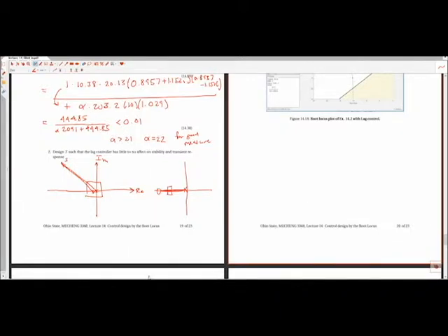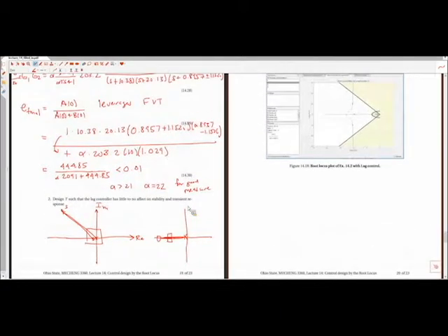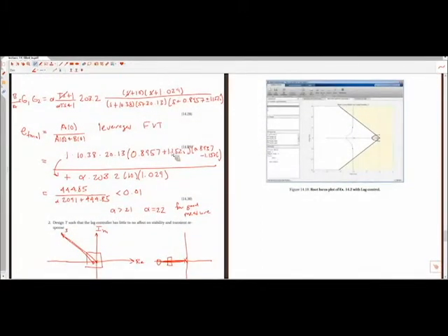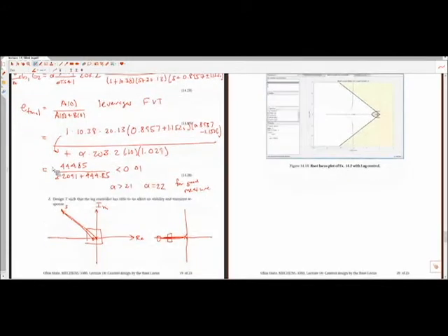So here we had a condition where we wanted the steady-state error to a step reference to be less than 1%. And we leveraged the content from lecture 12, which talks about steady-state errors, to understand what this single parameter in our lag control should be. We said alpha should be approximately greater than 21. And so we said, just for good measure, we'll make this alpha design variable 22.